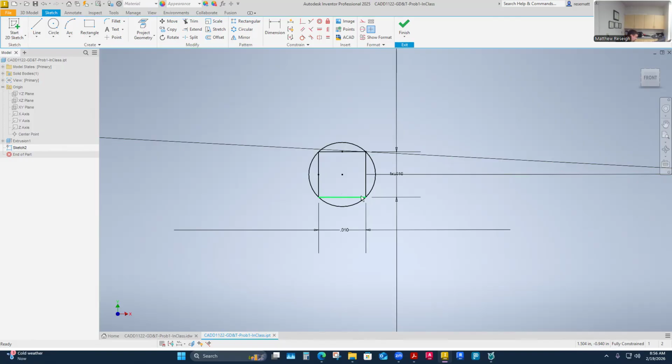I highlighted it in my book because it said, in comparison to conventional methods, the use of positional tolerancing, which is the GD&T concept I'm using here, provides some of the greatest advantages to mass production. The conventional coordinate dimensioning system limits the actual location of features to a rectangular tolerance zone. Using positional tolerancing, the location tolerance zone changes to a cylindrical, round shape, thus increasing the possible location of the feature by about 54%. It's right on the left-hand side of page 449, right in the middle.